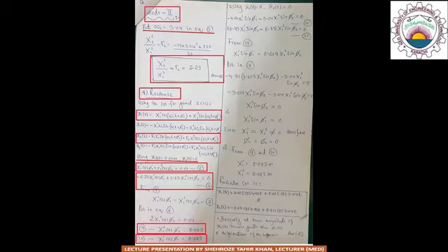Since these two equations indicate that the value of mode shapes cannot be equal to 0, therefore in order to find out the mode shapes, the value of the phase angles may be substituted as 0, such that at the phase angle 0, the trigonometric function cos will become 1. Therefore, we have x21 is equal to 0.005 and x11 is equal to 0.005 meters respectively.